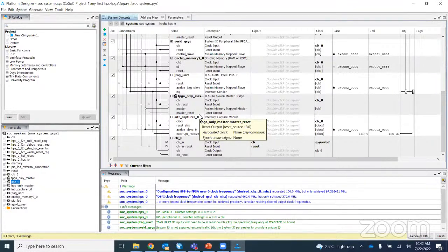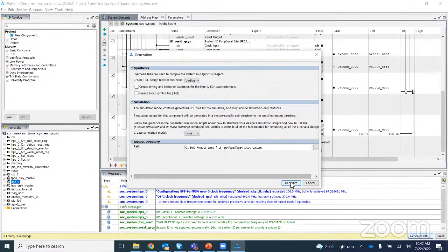Generate the HDL and then generate the QSys file, integrate that in the Quartus Prime design software, compile and understand what is happening. Later, you can take that design, customize it and use it for any kind of application. Right, now what we can do is, after we explore this, click here, generate HDL. And then you can click generate.